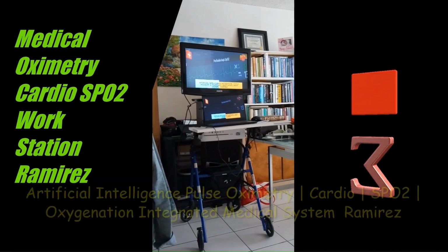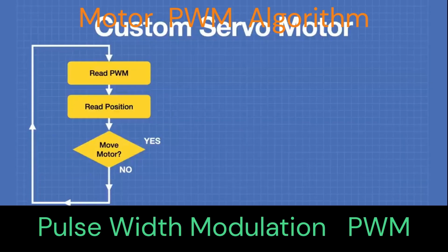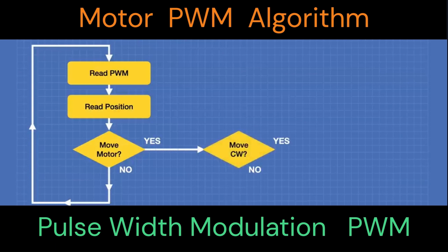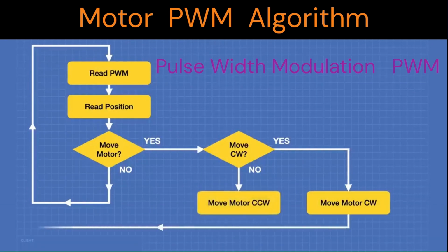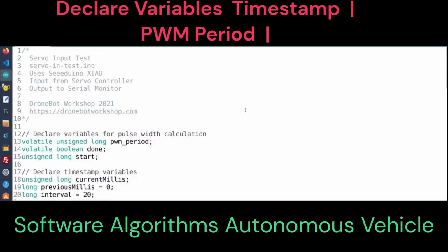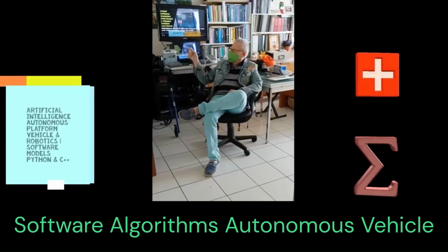The main neuromorphic architecture and CPU. Autopilot controls the motor driver via pulse width modulation signals, that is, the PWM signals. These signals have different levels in order to determine the direction and movement. A high-level signal will drive the artificial intelligence vehicle system forward, while a low-level signal will drive the artificial intelligence robotic vehicle backwards.